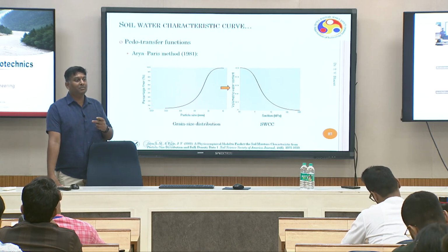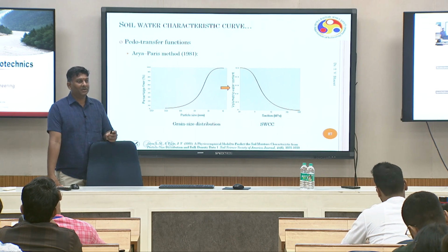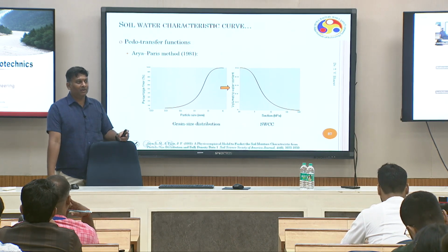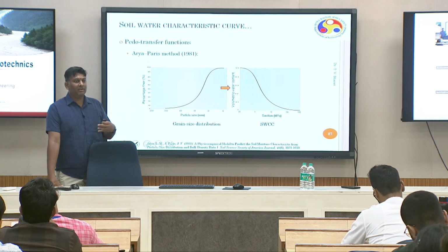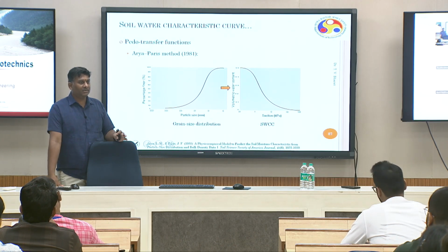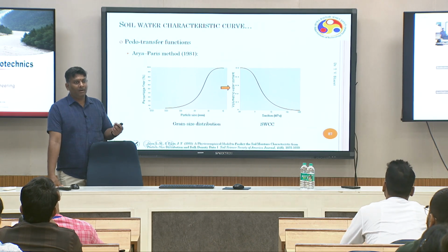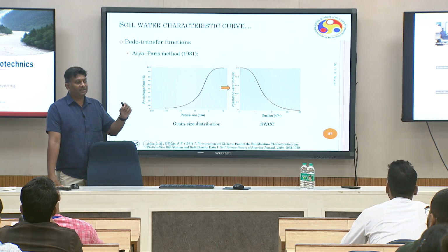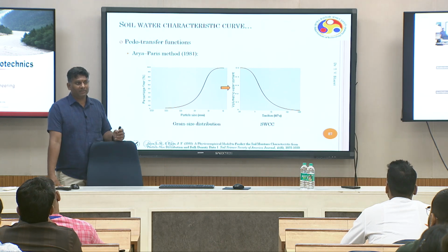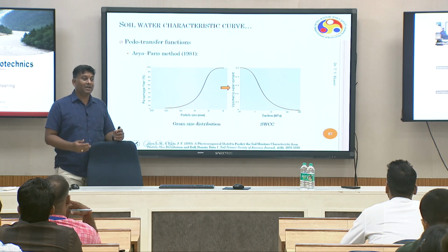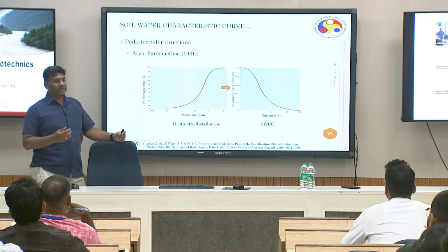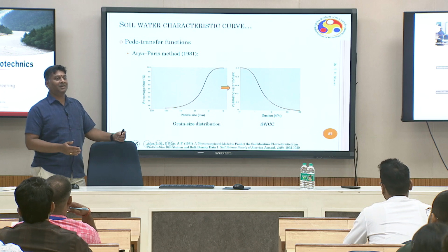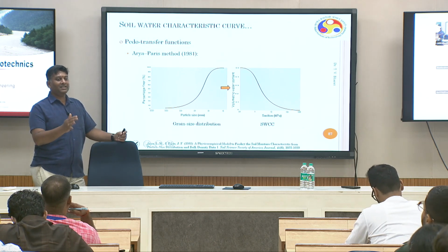We actually evaluate the temporal variation of factor of safety with incessant, continuous rainfall. Using several evaporation and infiltration models, we evaluate how the shear strength is changing within the soil mass. Based on that, we evaluate the factors of safety. Factor of safety is now a time-dependent quantity with change in the moisture content. So we can in fact predict when the landslide is going to take place.